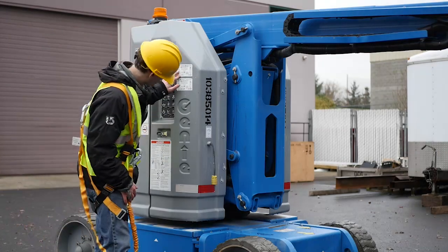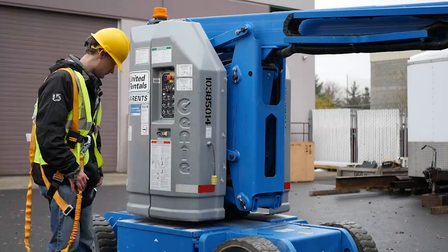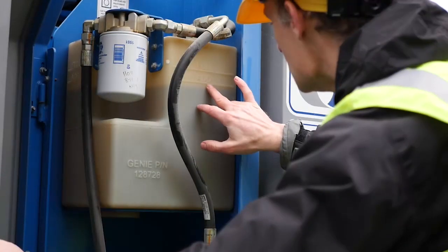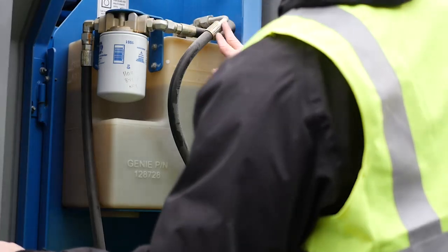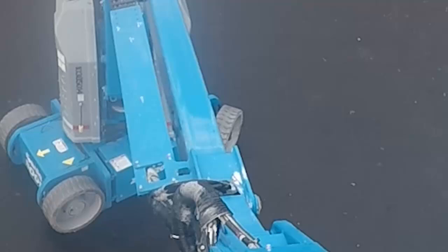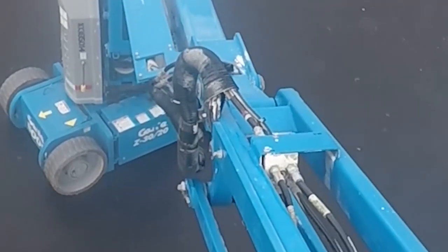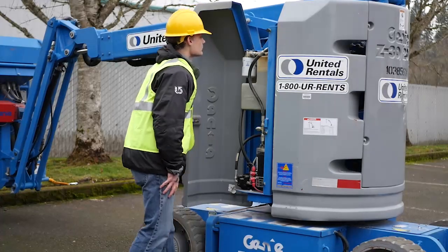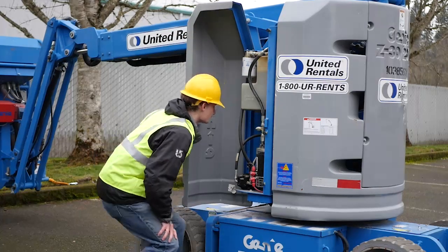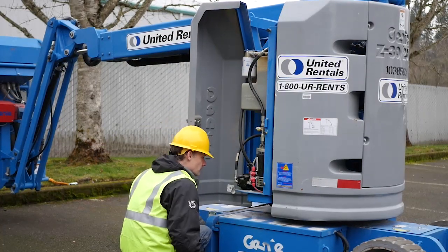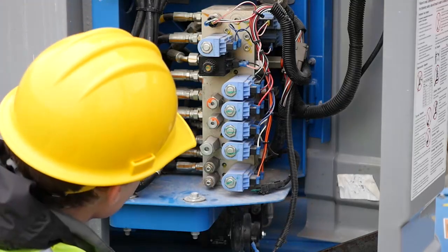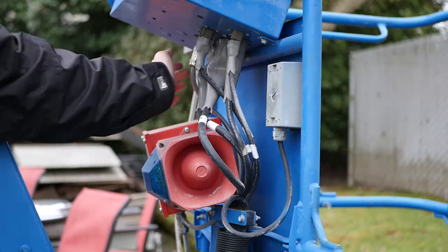Check for validation that the vehicle annual inspection is current. Check hydraulic and pneumatic systems for observable deterioration and excessive leakage. Check the fluid systems levels. Pneumatic and hydraulic control systems operate under pressure. Leaks in these systems can cause injury to employees, expose them to hazardous chemicals, and create a slippery and unsafe work area. Check the electrical systems for damage, signs of excessive deterioration, dirt, and moisture accumulation.